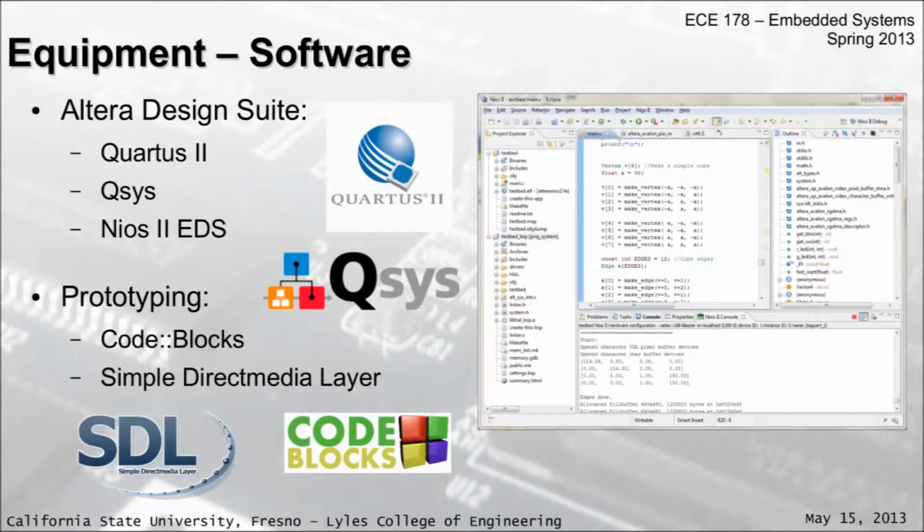Software is a little more involved. We're using Altera's design suite, that is Quartus 2. That's their digital design software for just general purpose design. So if you're designing an IP core, anything like that, you'd be using Quartus 2. Also for compiling HDL designs, you would also use that. Next, we'll be using Qsys. Qsys is Altera's main integrator when it comes to IP cores. Put them together, make a system.